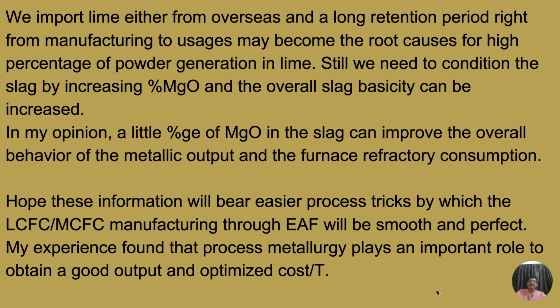In my opinion, a little percentage of MgO in the slag can improve the overall behavior of the metallic output and the furnace refractory consumption. Hope this information will bring easier process tricks by which LCFC or MCFC manufacturing through EAF will be smooth and perfect. My experience found that process metallurgy plays an important role in obtaining a good output and optimized cost per ton.